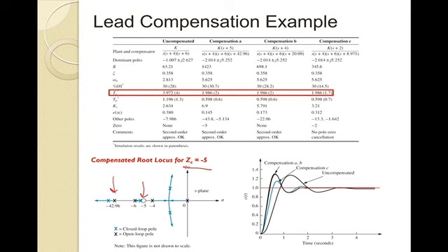Now what's going to happen with this root locus, we have our comparison. So here's this one, case A, for s plus 5. Here's one where we put the zero at 4, and then here's one where we have the zero at 2. Okay, so you can actually see the second case would be essentially a pole-zero cancellation there, and then the other case would be here. So we're only showing you the root locus for that one case, but here I'm showing you two other cases.